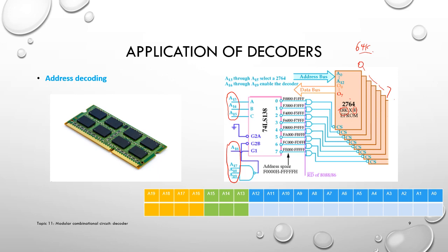Basically we can use an example to talk about this. Say I want to reach location 100 in chip 5. Now how do we configure the address bus? First, A19 to 16 is used to enable the decoder, so their value will be fixed. It has to be 1.